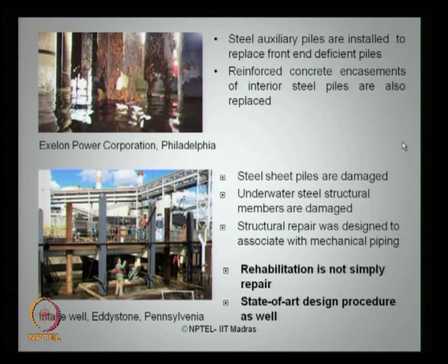The reinforced concrete encasements of interior steel piles are also done and they have been replaced, whereas in the Eddystone, Pennsylvania intake well, the steel sheet piles which have been used are extensively damaged. The underwater steel structural members are also found to be extensively damaged. Structural repair was designed in association with a mechanical piping system, which is an integral part of this intake well. Therefore, rehabilitation is not simply a repair system, it is actually a state of the art design procedure as well.